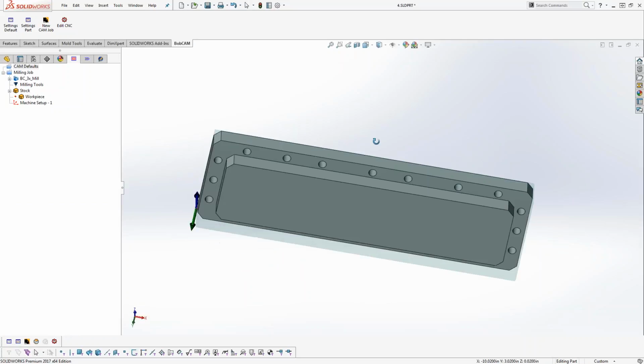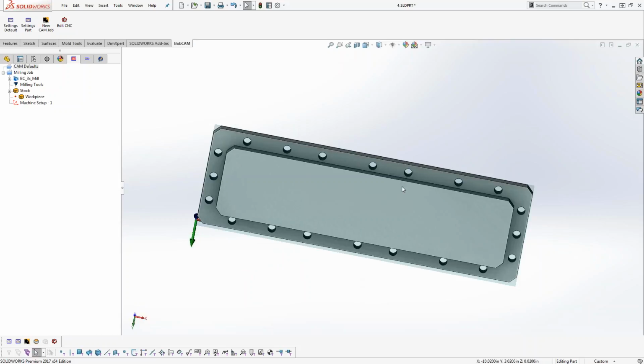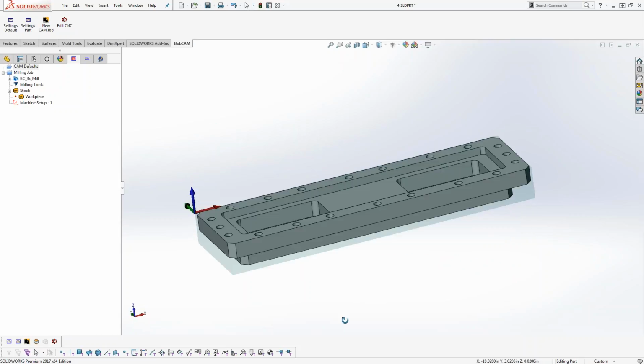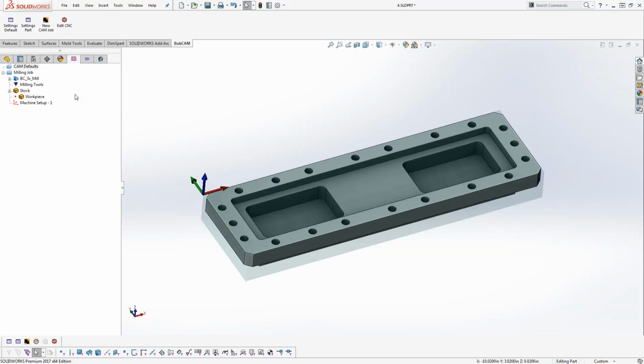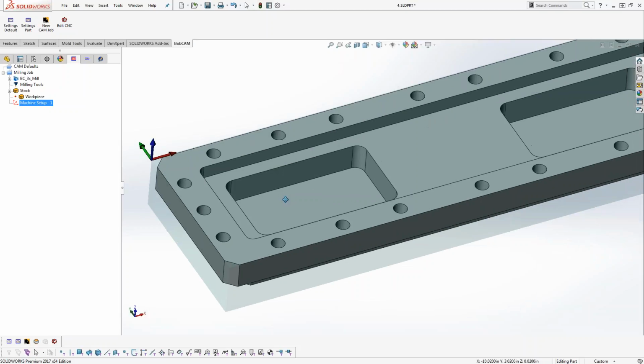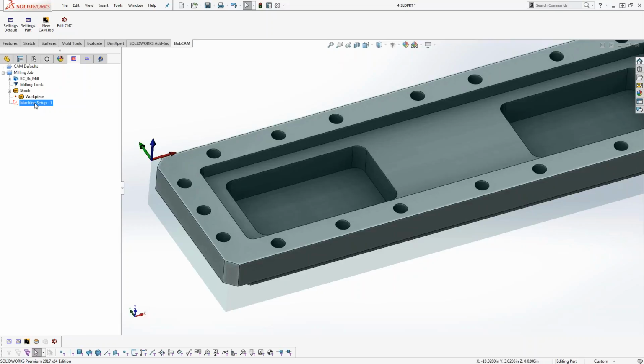One of the things you'll notice is, on this part here, I don't really have a sketch or a rectangle that represents the stock geometry or the stock size. Which is okay. I'm just going to pick up this loop here, kind of like what I'd been doing in yesterday's webinar. So we're going to go into the CAM tree, and I know this is different. Some systems have icons to load in your tool paths, like if you're drilling or pocketing, you would go to an icon. With BobCAM, this is all going to be found within the job tree.